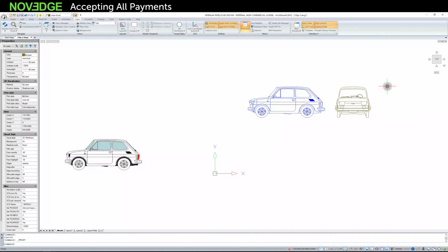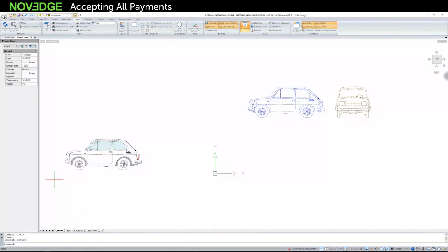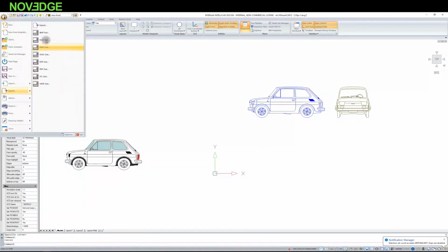Exactly what we have in this drawing. So the sheet will approximately look like this. Of course, without the roof being cut off, but it will have a similar format. However, we have no control over this process. That's why I absolutely do not recommend using the export to PDF option directly from the model.